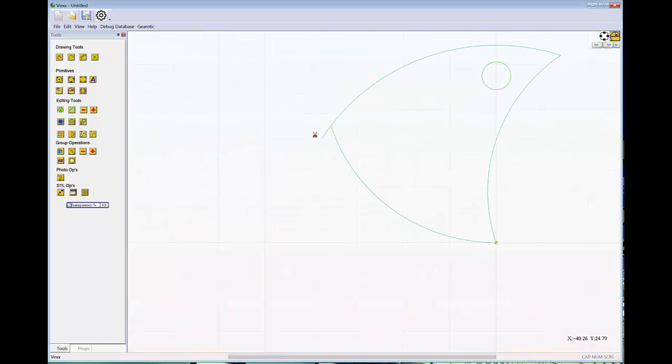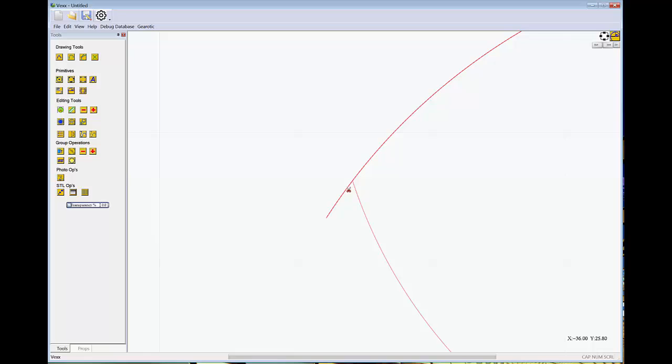And now when you come up, a new contour has been selected and you may be able to trim it properly. I can't in this case because I still have an overlapping self-intersecting contour. So I'm going to use my Shift key, zoom in, use my left Shift to click very close to those 2 points.